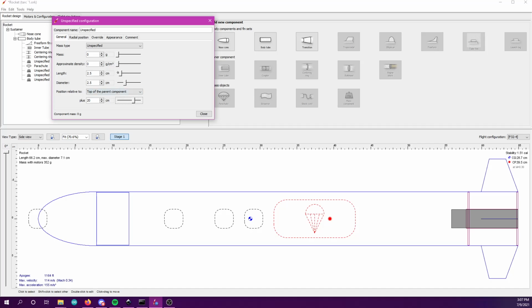We did this a lot during launches. If we got over height during a practice launch, we would put in mass to this spot, or if we were under altitude, we would take away mass. So we're going to be dealing with this a lot, and we don't want this to affect our stability margin, because that will add in additional variance which we're trying to eliminate.